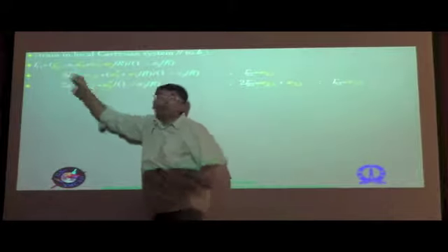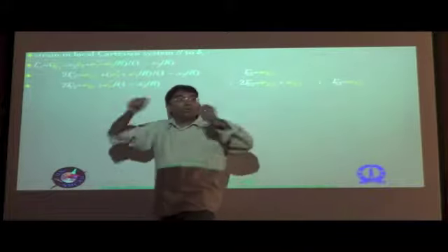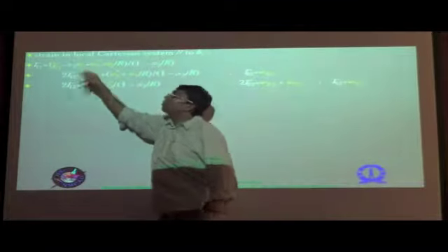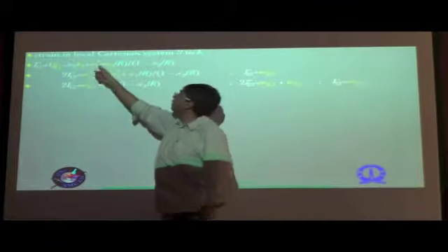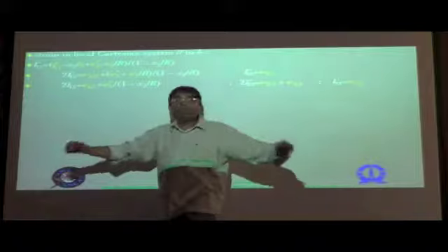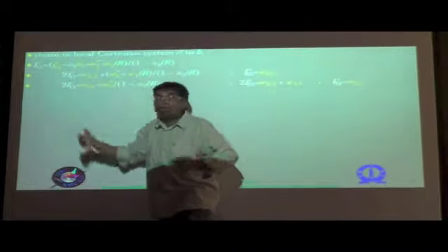The extension of the reference curve contributes to the extensional strain, the curvature also contributes to the extensional strain depending upon how far it is from the neutral axis, right? And then of course the warping, but this is a very small contribution, W1 in itself is small, and then you're taking a derivative with respect to x1, which is along the length, the largest dimension in the entire structure. So you can see that those are the 2 leading terms. Similarly, you can see the others are quite intuitive as well.